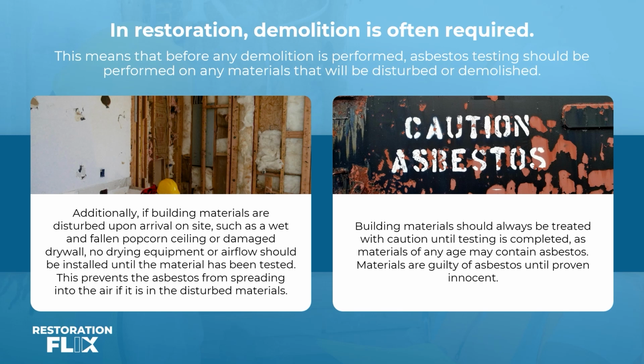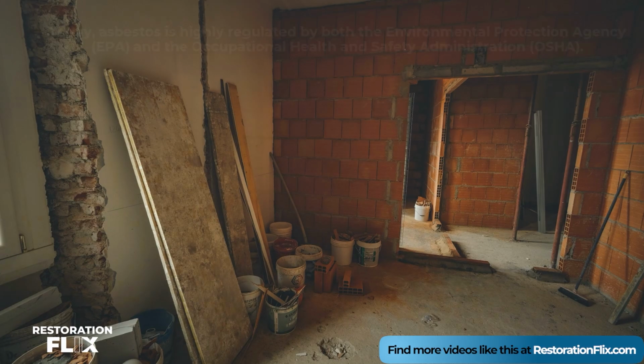Building materials should always be treated with caution until testing is completed, as materials of any age may contain asbestos. Materials are guilty of asbestos until proven innocent.